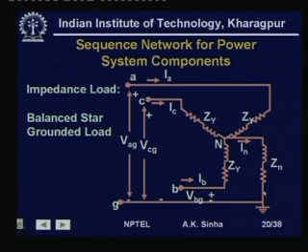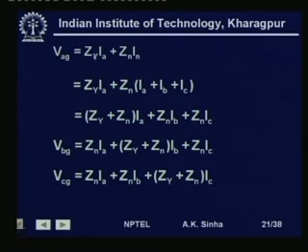So, IN into Zn is the voltage rise here, and IA into Zy is the voltage rise here. So, from here to here the voltage VAG is nothing but the sum of these 2 voltage rises, or the voltage drop if we are seeing the current flowing from phase A. So, VAG is Zy into IA plus Zn into IN.